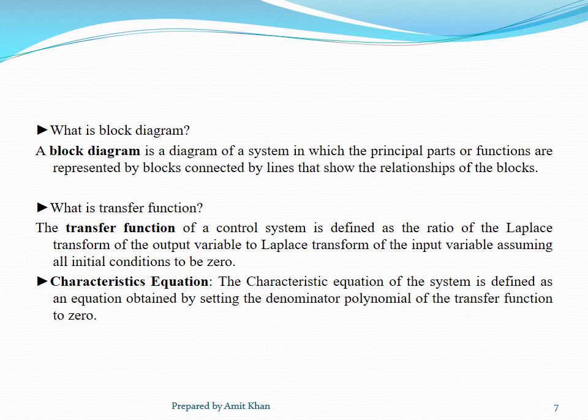Next is, what is transfer function? The transfer function of a control system is defined as the ratio of the Laplace transform of the output variable to the Laplace transform of the input variable, assuming all initial conditions to be 0.